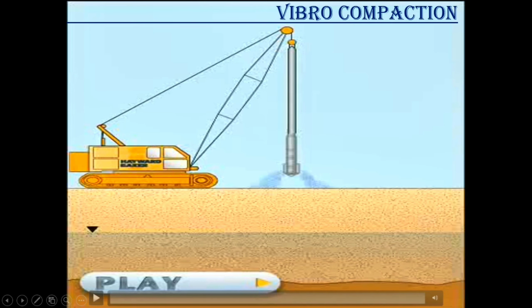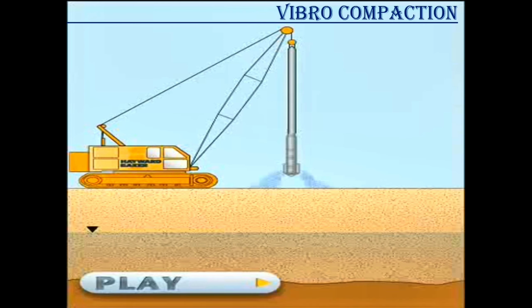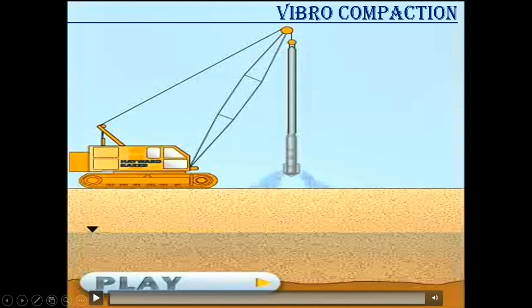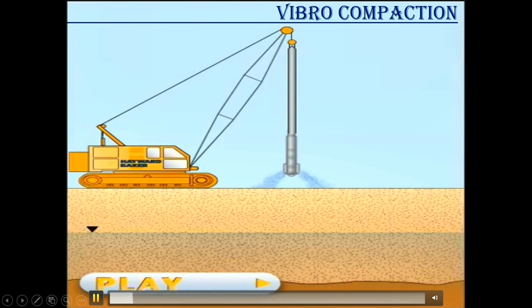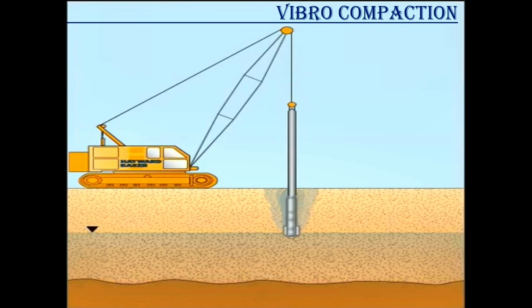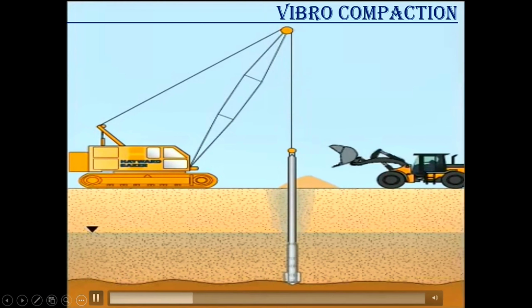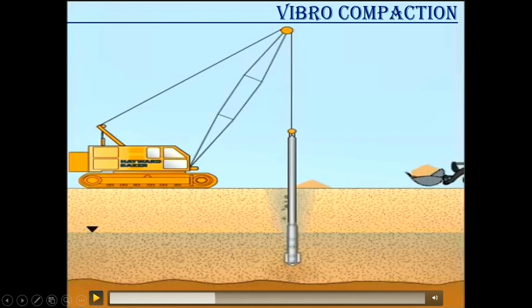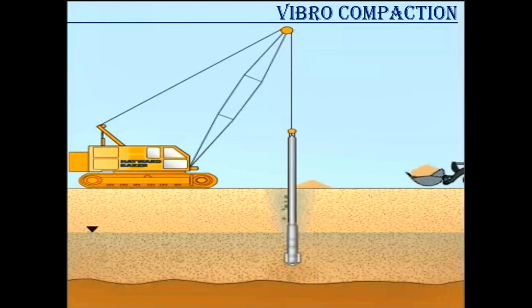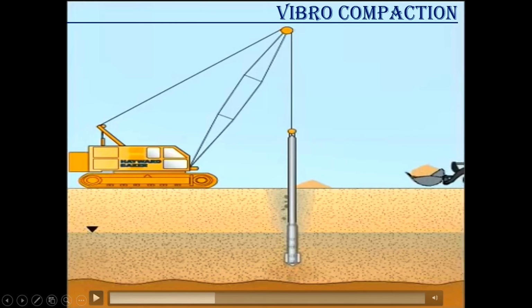Now the next one is Vibro Compaction grouting. As we indicated earlier, Vibro Compaction grouting and jet grouting are almost the same. Clear? So this is the process by which we choose Vibro Compaction. As the name indicates, we go with vibration, but only one thing differs. In Vibro Compaction grouting, instead of using grout, we provide sand, and that sand is laid down on top of the ground, and because of vibration it starts to go in, and that hardens my strata entirely.